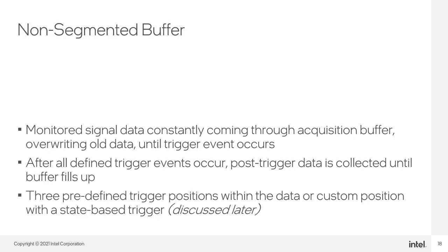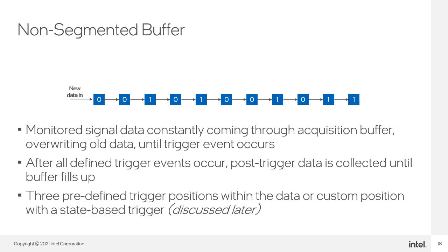A non-segmented buffer is more familiar and what is typically used on external test equipment. The buffer behaves like a FIFO. Newly sampled data is constantly brought into the buffer and shifted through. The oldest samples are removed at the end of the buffer.